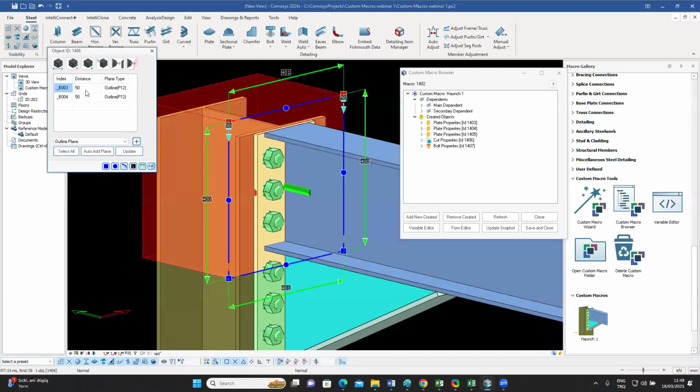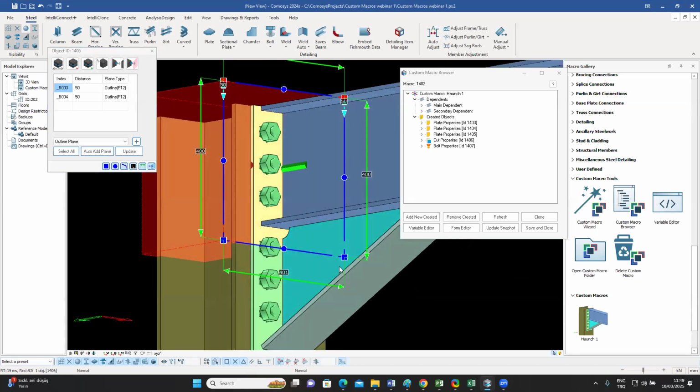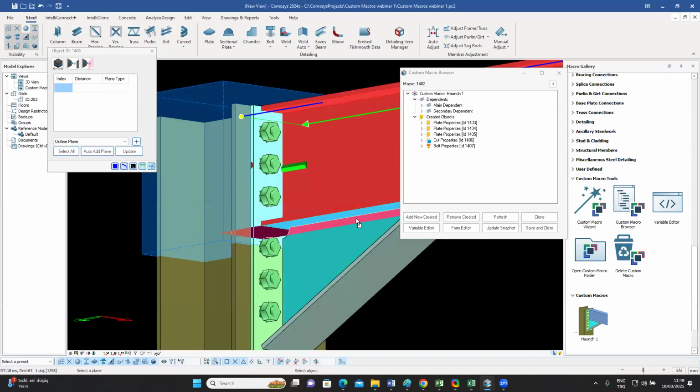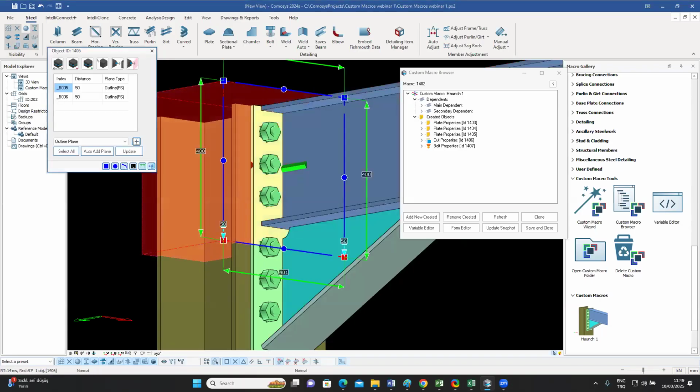This time it automatically finds the distance 50. It's bound to the top plane of the beam by a distance of 50, which means wherever the top of the beam will be, the cut will be 50 above that. So it's never going to go down. Similarly, I can select the bottom two points of the cut, this polygon cut, and give another binding, select the beam, and give the bottom plane of the beam now. When I do that, it creates another 50 for the bottom two points.